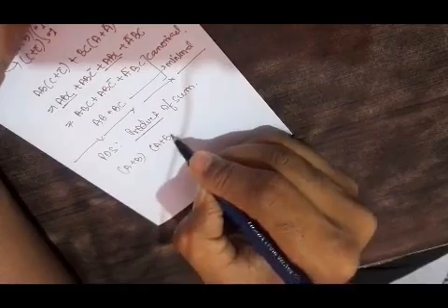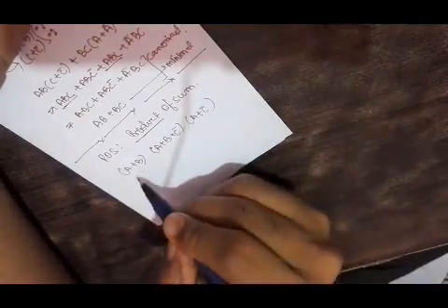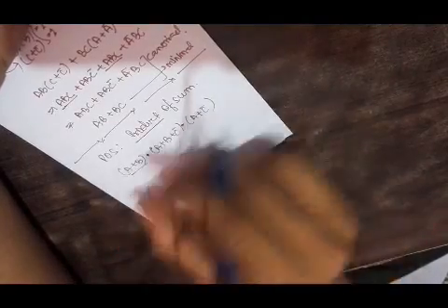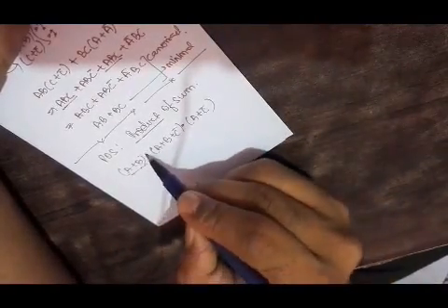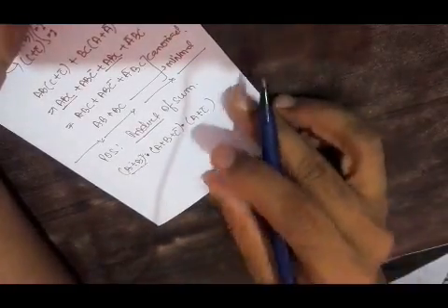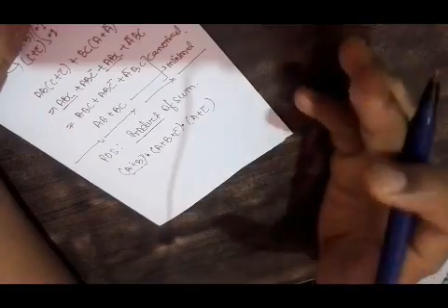A plus B plus C bar, and A plus C bar. Suppose these are the sums, then we need to take their product. So this type of expression is known as the product of sum. We have a product of what? Sums. These are sums, and then we have a product of them. So again, here we have a canonical and minimal form. The definition remains the same.